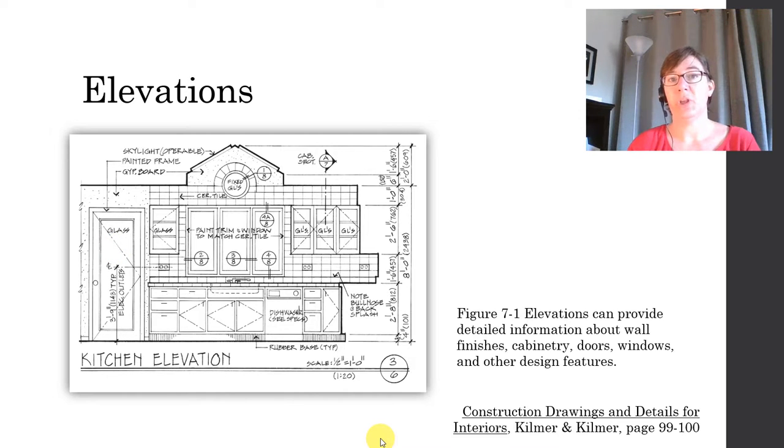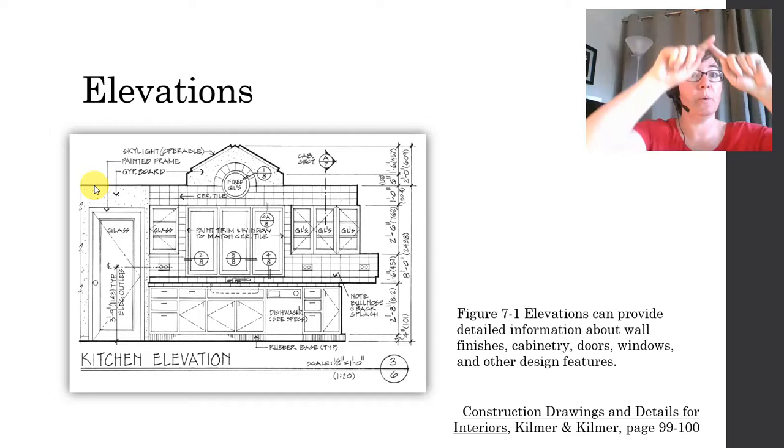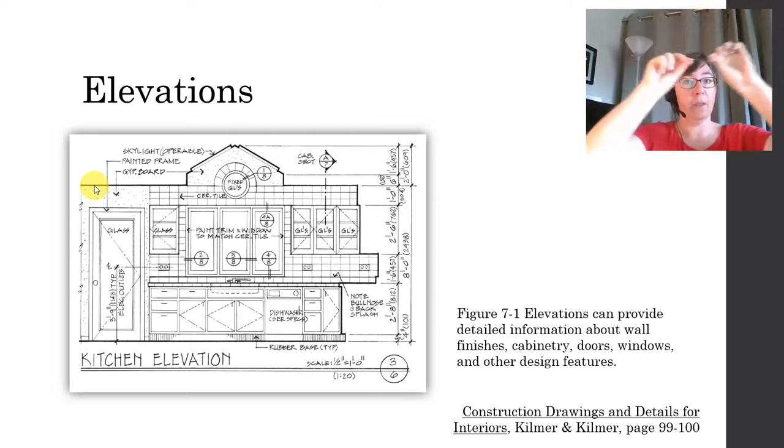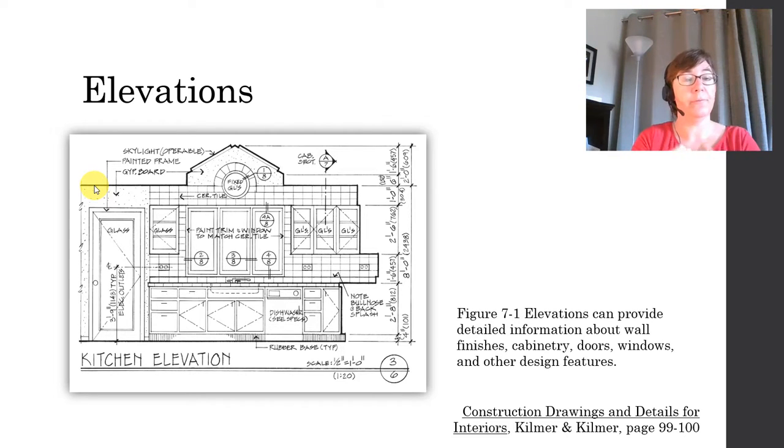This illustration is also a good example of line weights in this drawing. You'll see that there is a very heavy profile type line weight that goes around the exterior of the drawing, and this is typical for interior elevations. Anything that you cut through, which will be the profile of your ceiling, your walls, and your floor, is going to be a very heavy line weight.